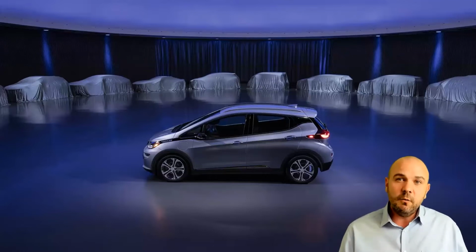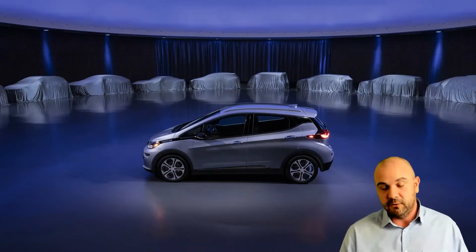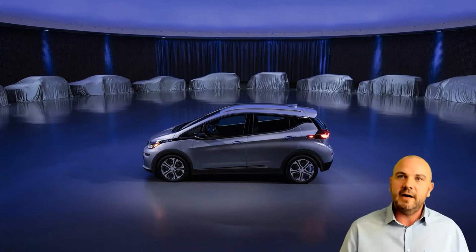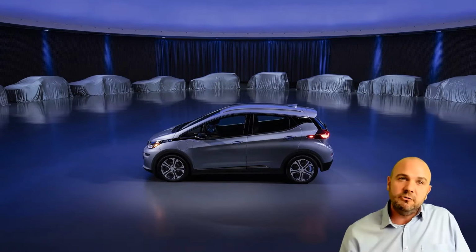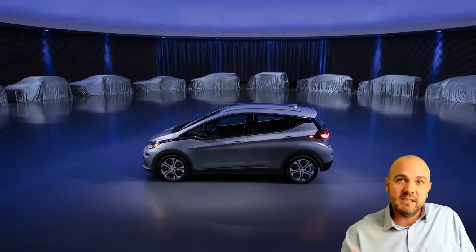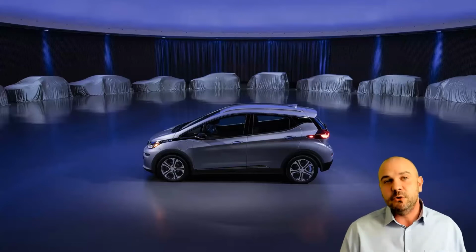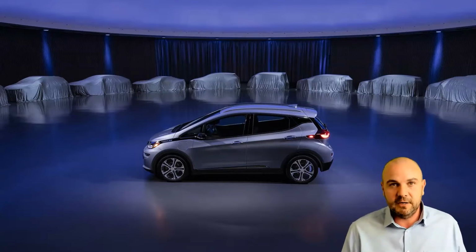And what do we all think about when we're looking at electric vehicles as a consumer ourselves? We all look at the range of the vehicle, whether, you know, I'm doing 300 miles a week, right? I need a vehicle that's got as high a range as possible. And one of the biggest things with electric vehicles that affects the range, because the batteries can only take you a certain way, is aerodynamics, yes, but weight is a massive contributing factor to the range of an electric vehicle. So removing material and being as light as possible is very advantageous to the electric vehicle.